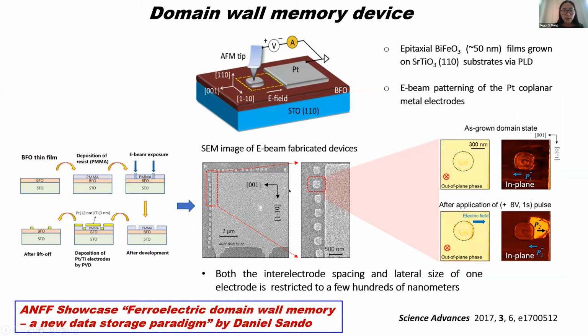Using e-beam lithography and e-beam evaporation, we prepared very small nanoscale devices on the BFO. Then using scanning probe microscopy, we can create and erase these domain walls, which are conductive in BFO films, and realize the memory function.